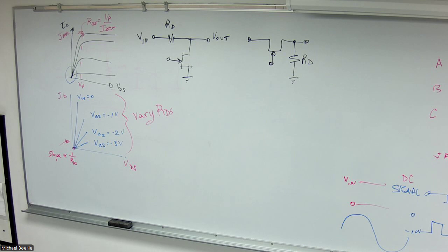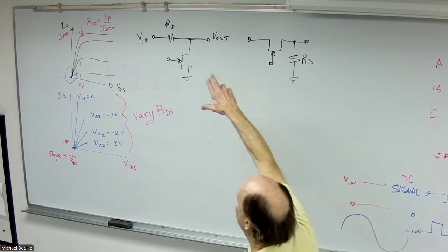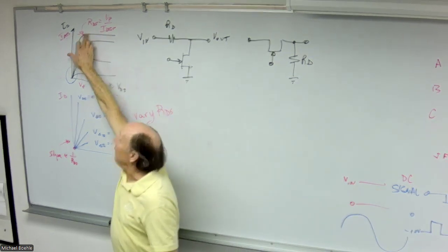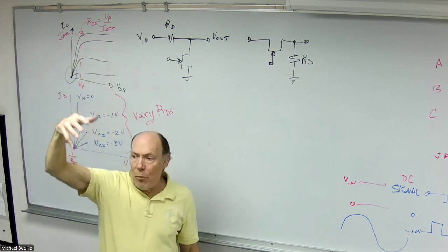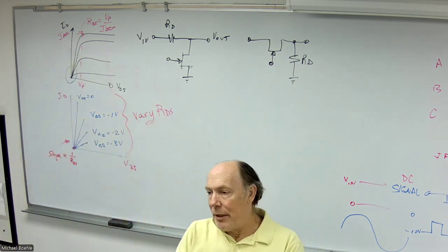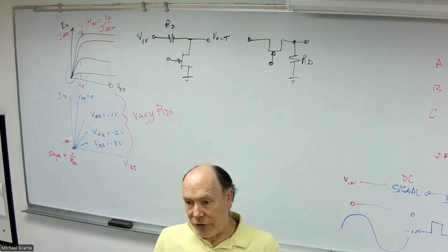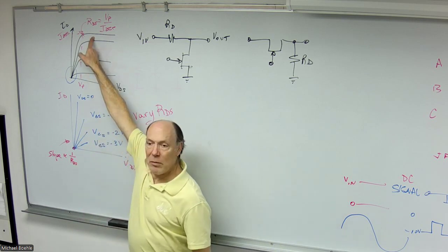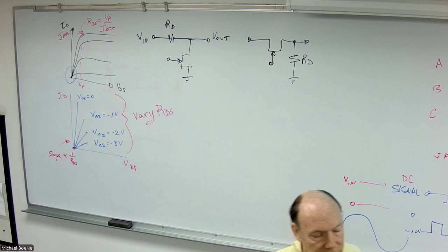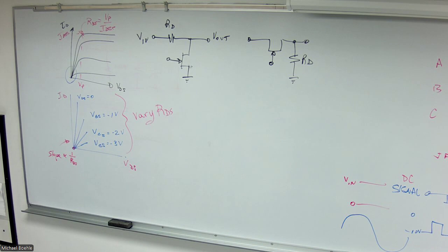I can use it for current limiting, right? Because remember that when I have my JFET set up, we go back to here, there's an automatic current limit that's going to happen that will limit the current. So I can operate somewhere where I'm maybe controlling the amount of current, but in the event of something, say the load shorts out or anything like that, that's your maximum current. Done. Stuck there, whatever happens. All right, so a few other options like that.